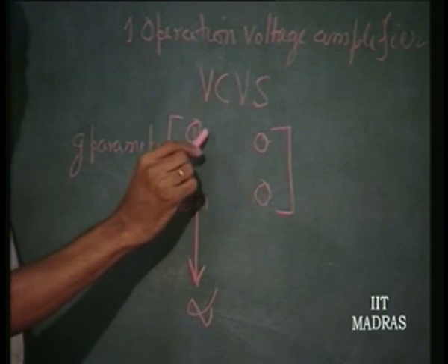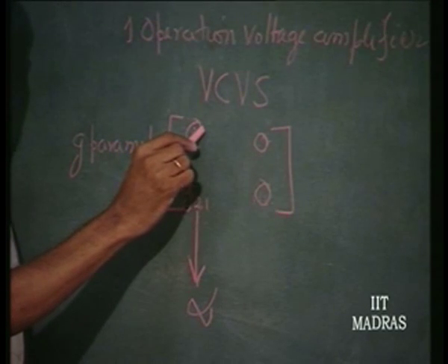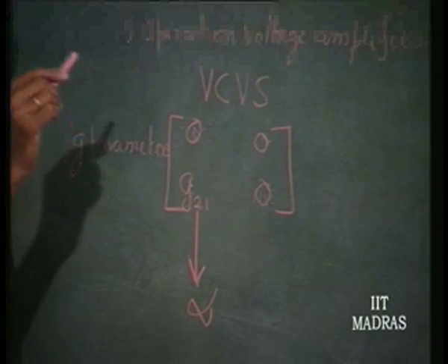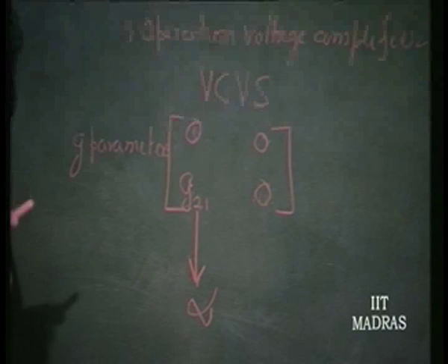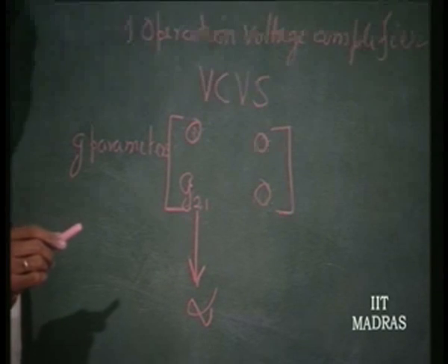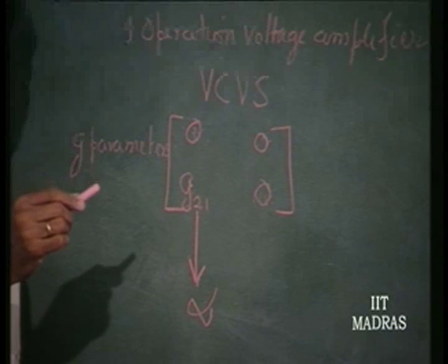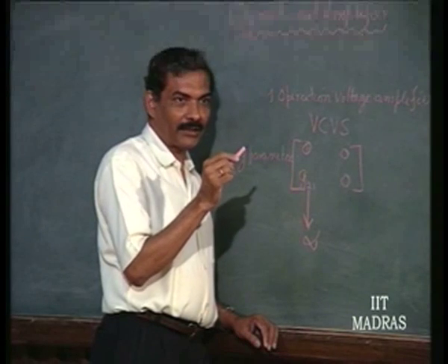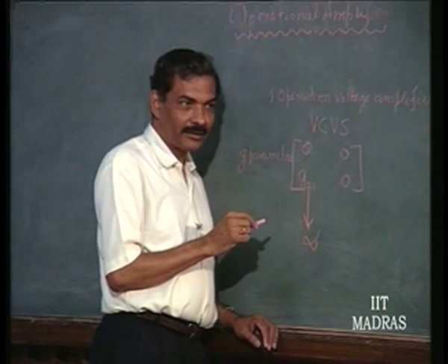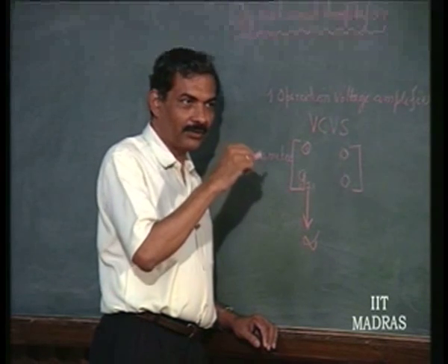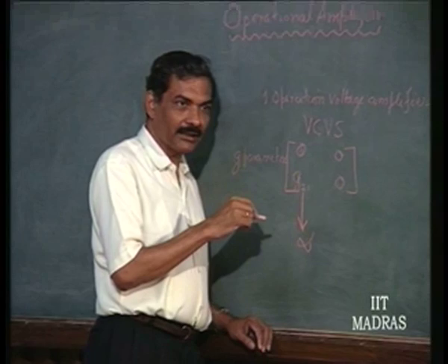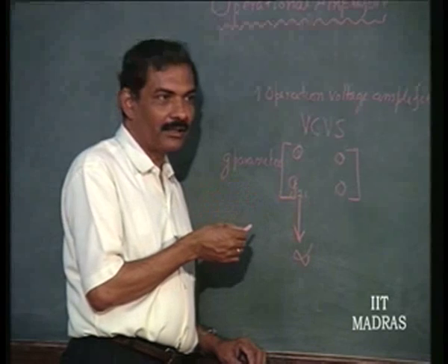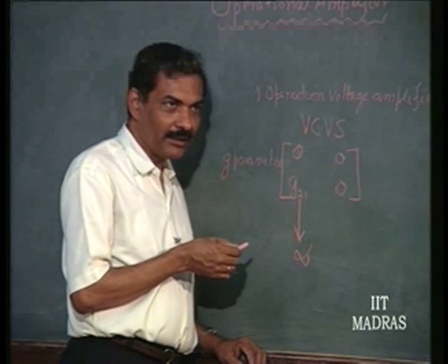very low current if they are bipolar stages. You remember this? Because Re is nothing but Vt divided by Ieq. When Ieq is made low, automatically Re is going to be low. But you have to take care that beta of the transistor does not decrease too much. So, we should not go to very low currents where beta also decreases, so that this increase in Re is just compensated by the decrease in beta, and you do not achieve much of a change in input impedance.